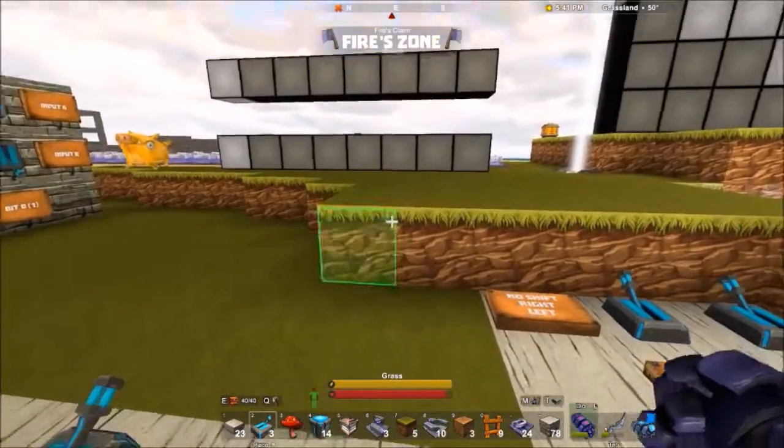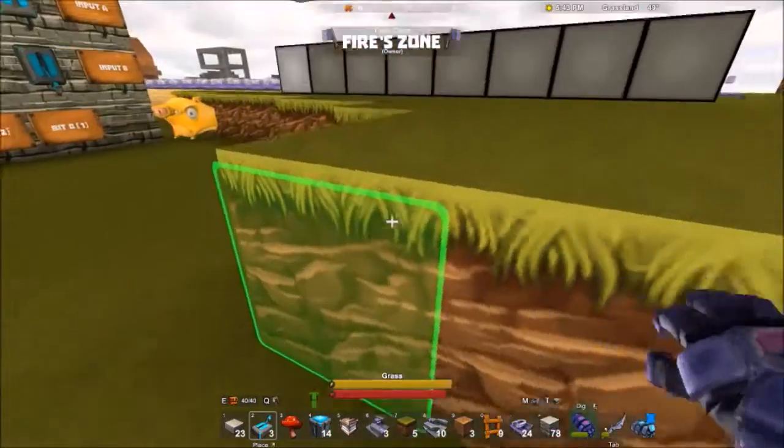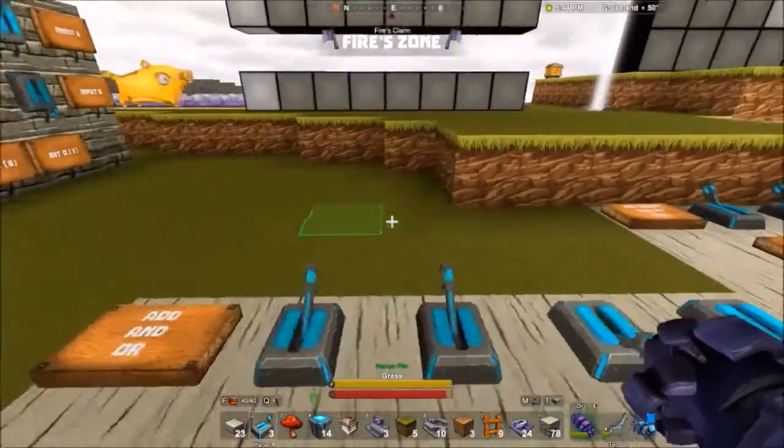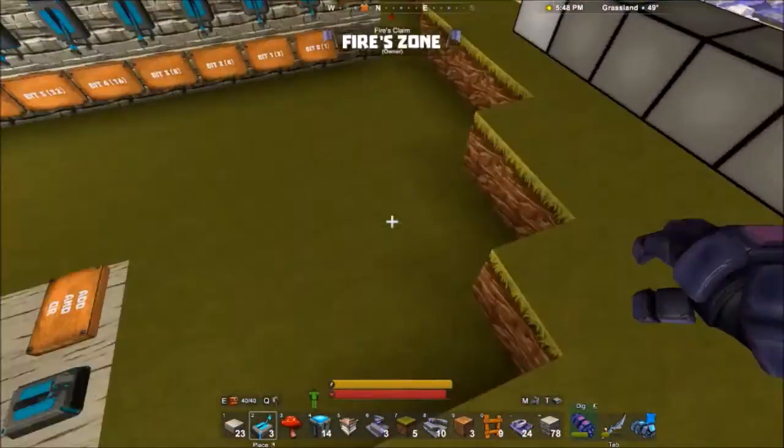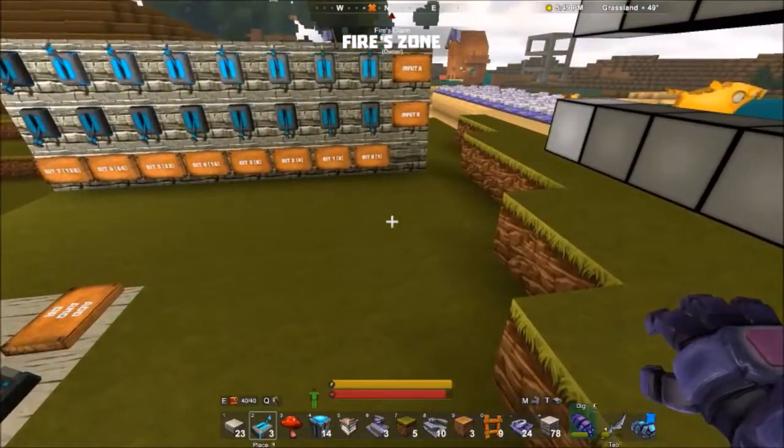This video I'm going to be showing you the difference between the ripple carry adder and the look-ahead carry adder. The look-ahead carry adder is the one that I'm implementing on the ALU. The ripple carry adder is the simpler version. It uses way fewer logic gates and is way simpler.